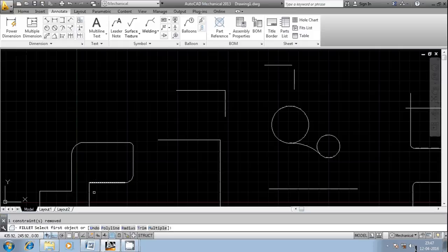So now we discussed all the options here. Polyline option in case of fillet, to generate the fillet. In case of polyline, always ensure that you are going to draw the polyline and perform the fillet operation. Then radius, how exactly we can vary the radius to get the different fillet values. And then trim option. So using the trim option, how exactly I can generate the fillet.